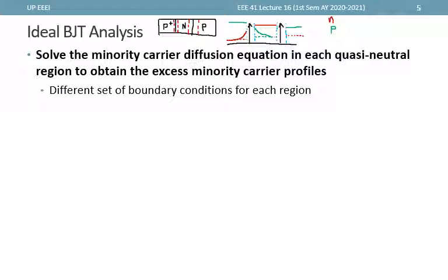So we have that plot for the minority carrier, whereas for the other side, if it is also in forward active, then the plot should look like this one. But what happens in the base? From our usual analysis, we need two boundary conditions, and if this one is forward biased as well, then we will expect some trend like this.